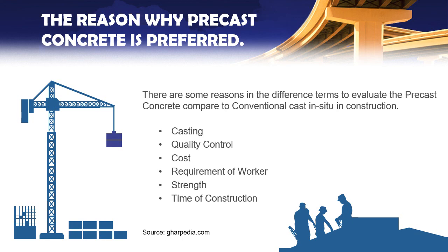In precast concrete, elements are manufactured in a controlled casting environment, and hence it is easier to control mix, placement, and curing. While in cast in situ concrete, such as columns, slabs, and walls, these elements are cast on site in the open environment, and hence it is difficult to control mix, placement, and curing.